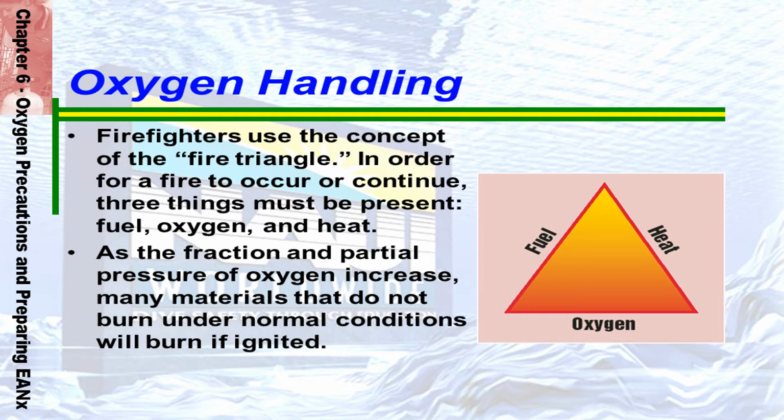Petroleum-based products and other hydrocarbons are of special concern because they ignite extremely easily in a pure oxygen environment. Other materials, though they may not become flammable, will oxidize and degrade much more rapidly in the presence of hyperbaric oxygen. When high pressures of oxygen are going to be present, extra care must be taken to prevent the fire triangle from occurring.